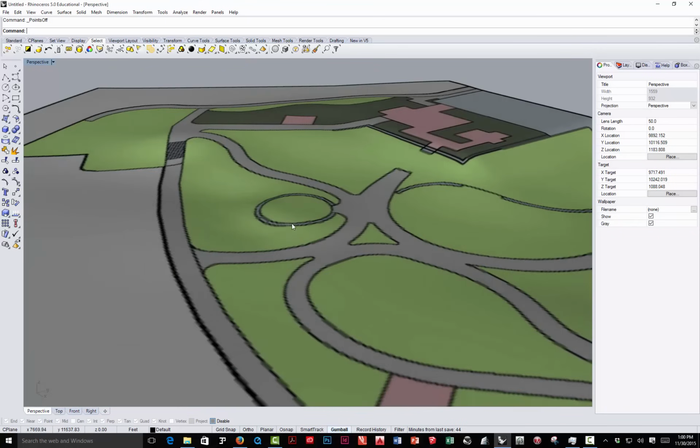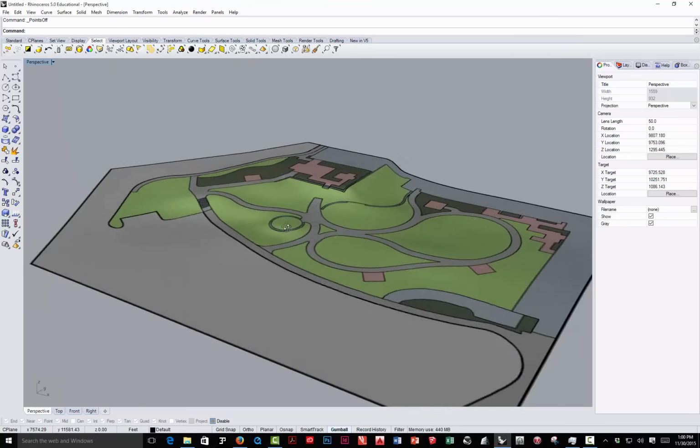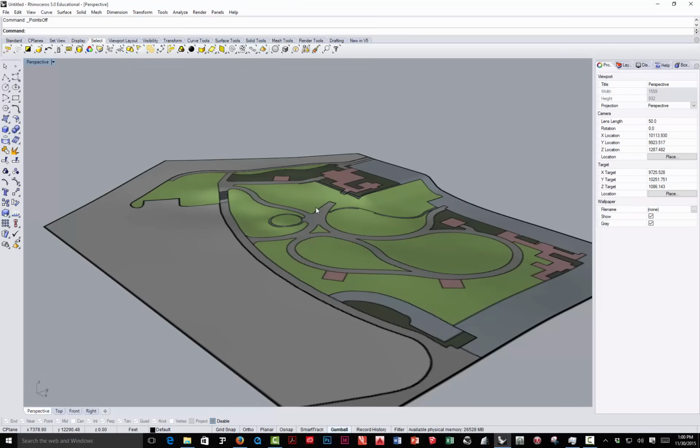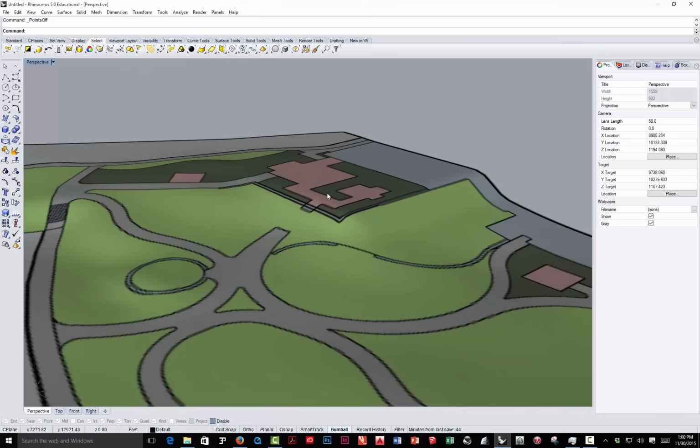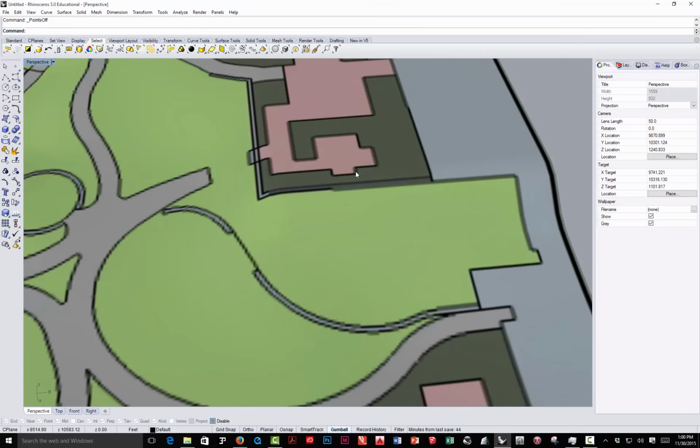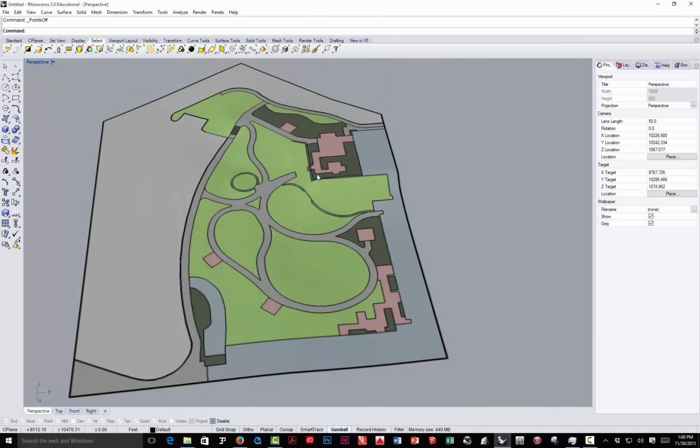Looks pretty good. And actually it does slope down a little bit over there. Okay, so that's a quick way. You use those show control points and you select them, use the set point to kind of create a level pad, and then you go in and manually adjust them a little bit if you need to. Now in this case, I still need to accommodate this wall in here.